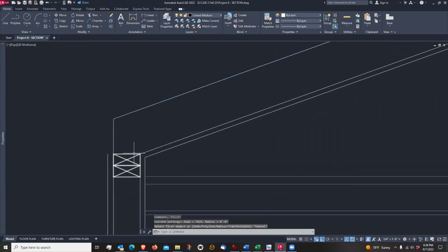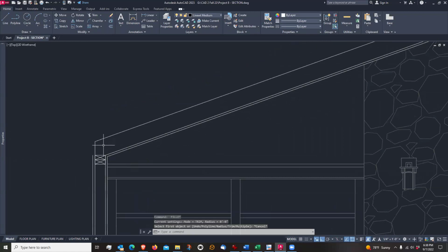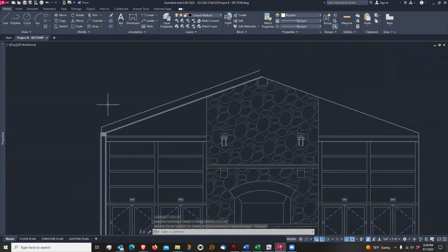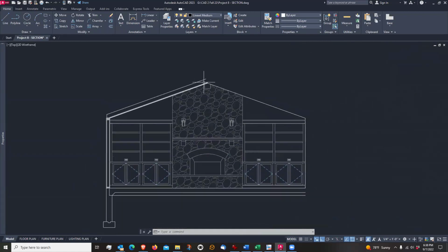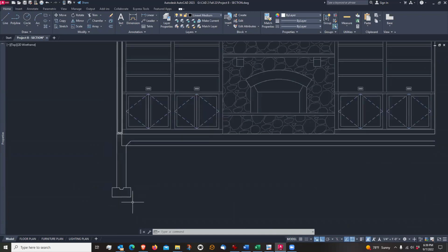So the rafter is notched a little bit here, and it is just sitting on this header plate. So the weight of the roof and the ceiling is carried down by the rafters, hits this sill plate, and then is carried straight down into the foundation. And then the footer here sort of distributes the weight onto the soil underneath it.